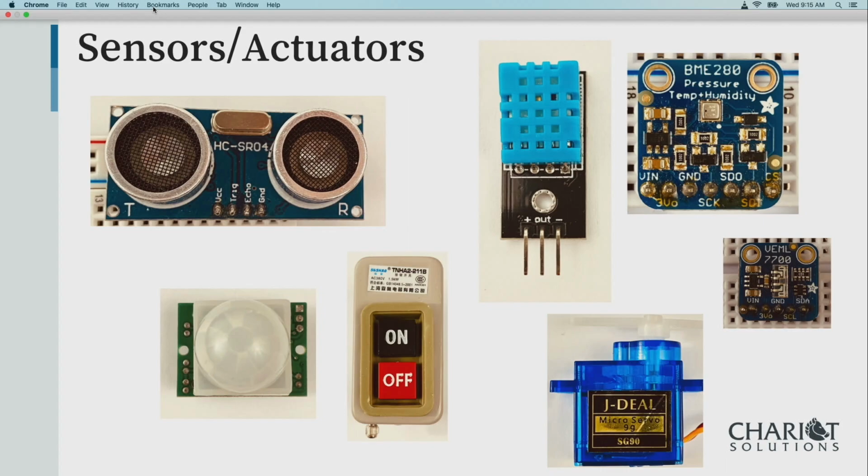So there are communications like UARTs, where you're actually communicating with a modem. There are communications like I2C and various GPIO, or general purpose digital and analog I/O communication signals. So depending on what you're connecting with signal-wise, you'll write code that actually reads and writes in that way. You're almost like writing a device driver in a way. You're writing at a lower level.